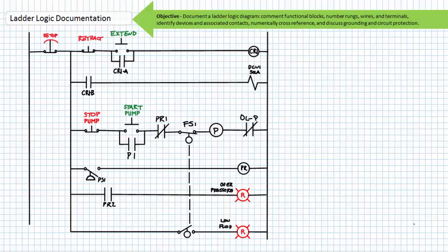This isn't my favorite method because method 1 clearly identifies two very important wires, 1 and 2, as the left and right vertical uprights. Method 2 is a little sloppy in that there is no predicting what wire number the right vertical upright receives. This being said, a lot of manufacturers use this scheme, and it's something you should be aware of. Method 2 starts similar to method 1.